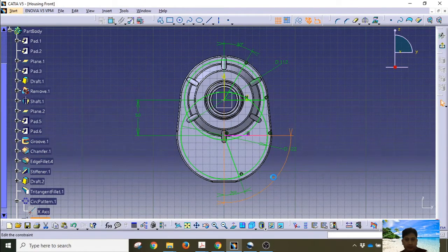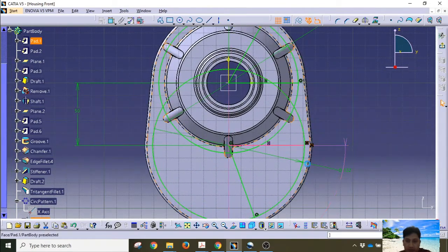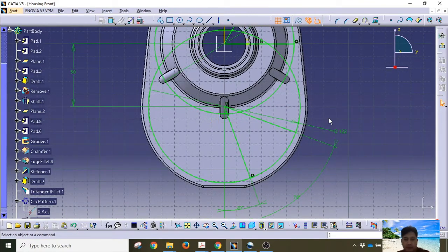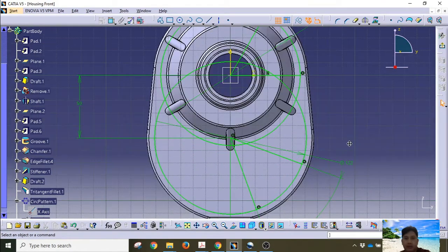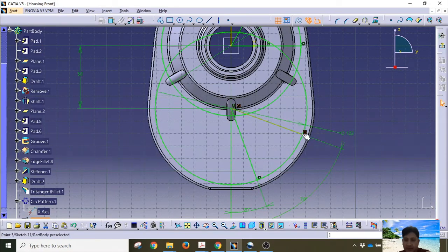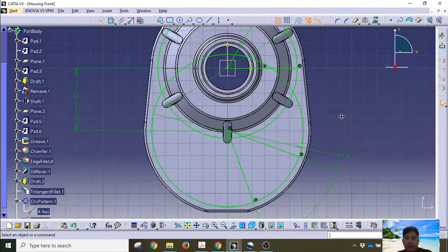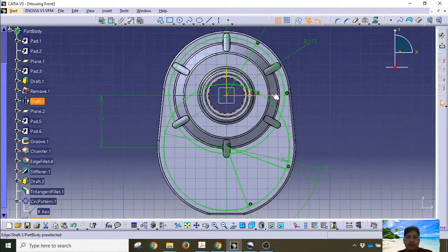And this line with this vertical line must have an angle of 70 degree. So because I created wait, this one is wrong. Yeah. So it should be the other way around. So I have to delete the constraint, horizontal constraint. This represent the connection between this endpoint of this line with the line of the circumference. Okay, so and this remain 90 degrees.